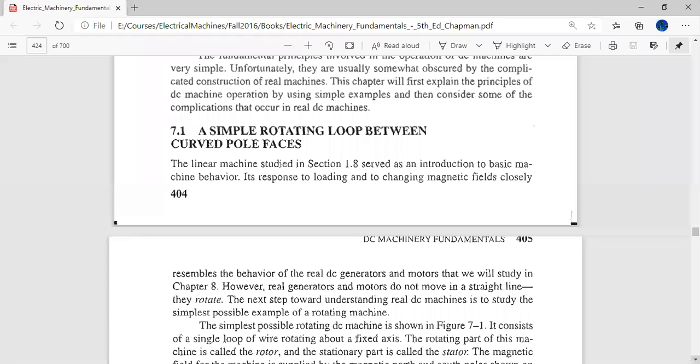And in the case of an induction motor, we provide the three-phase AC supply to the stator, and that produces a rotating magnetic field. So the main field is on the stator in that case, and we do not give anything to the rotor. The rotor basically induces the voltage. So in the case of induction motor, the armature is on the rotor, and due to the inductive effect, the rotor starts to rotate in the same direction as the rotating magnetic field produced by the stator.